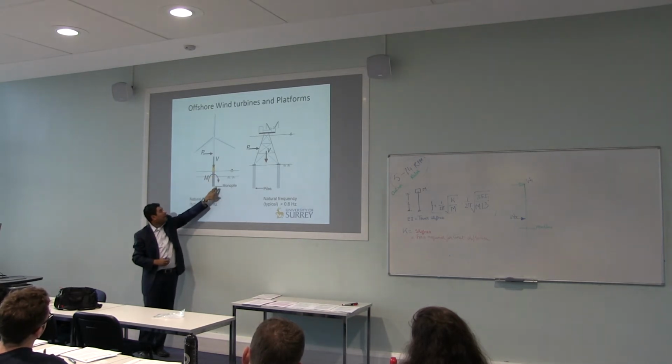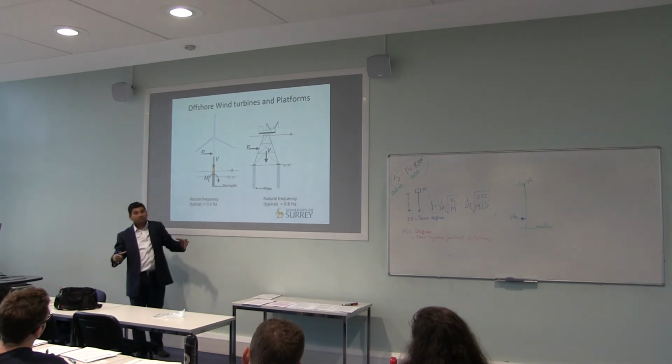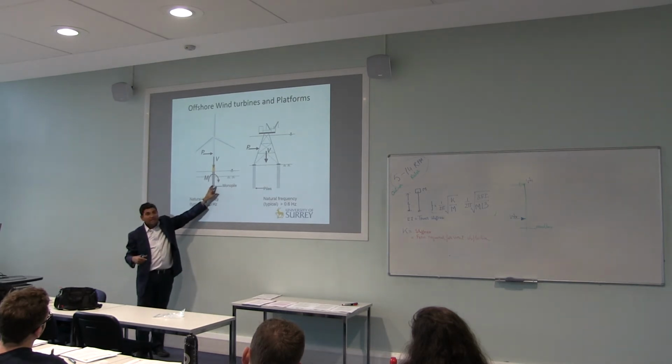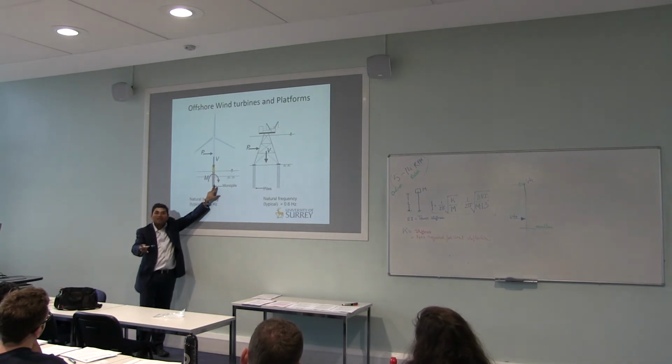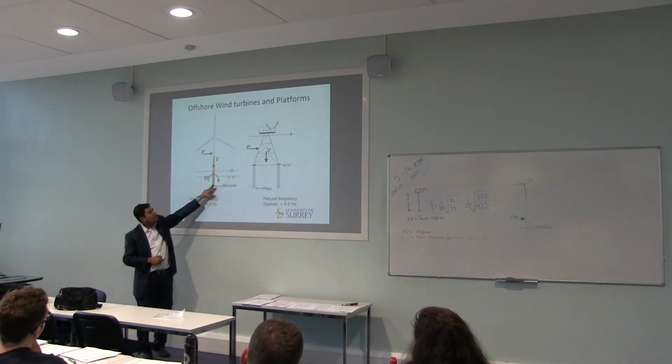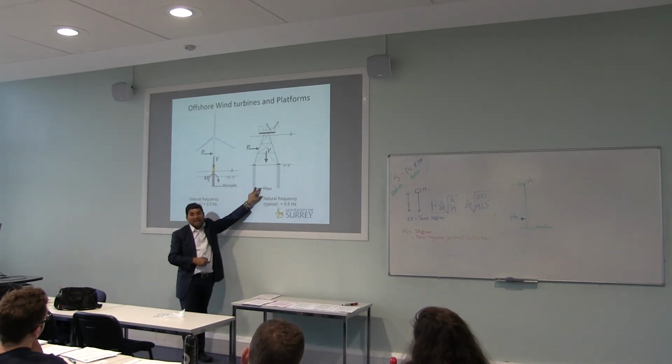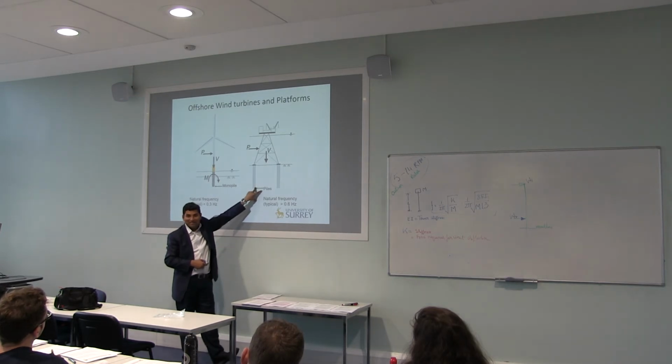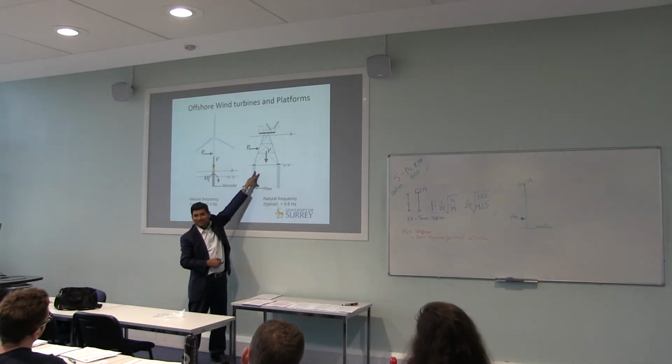And they are large diameter. So effectively, these piles are moment resistant. You design a pile to resist moment. On the other hand, those piles are there to carry vertical load and smaller lateral load.